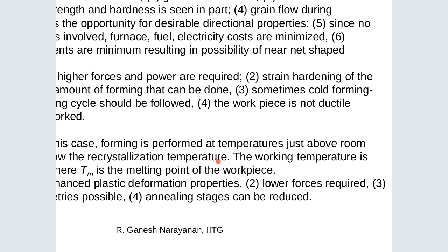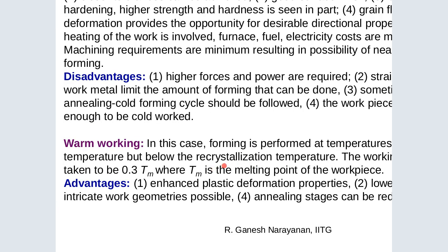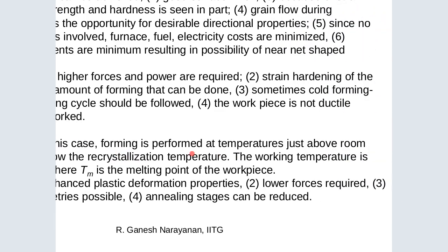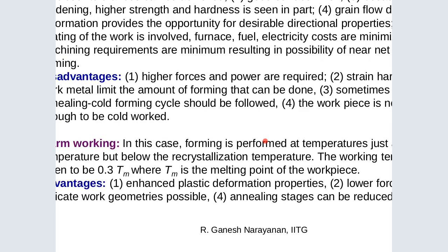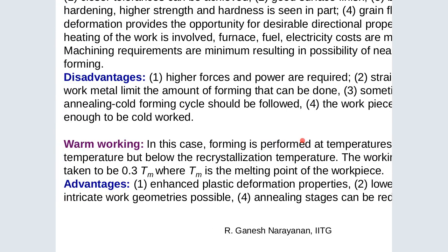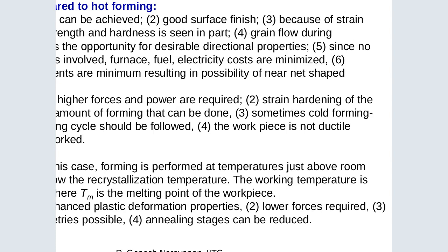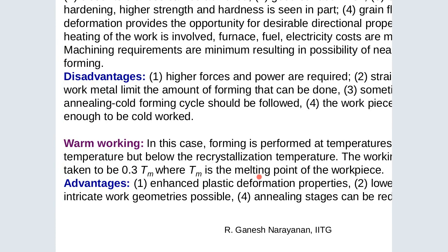And then the strain hardening of the work metal limits the amount of forming that can be done. And sometimes an annealing and cold forming cycle should be followed. That is a disadvantage. And then the workpiece may not be ductile enough to be cold worked.